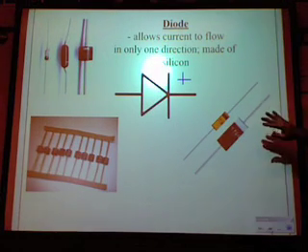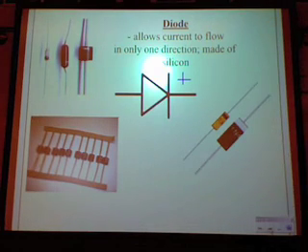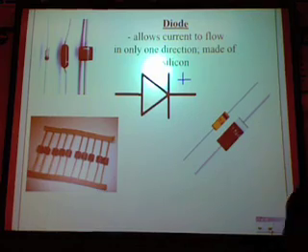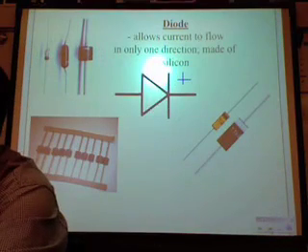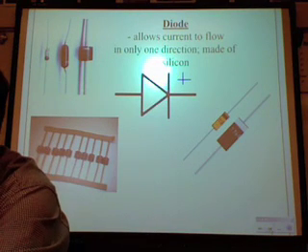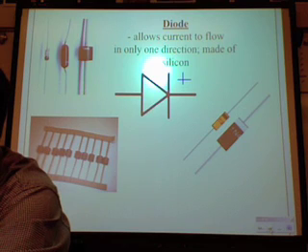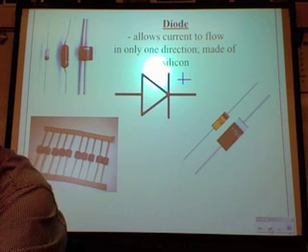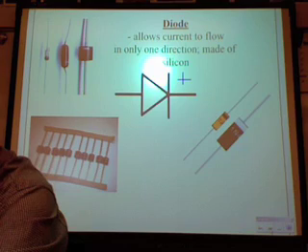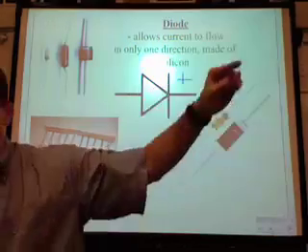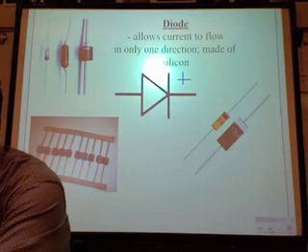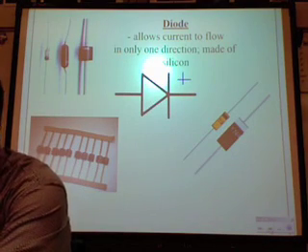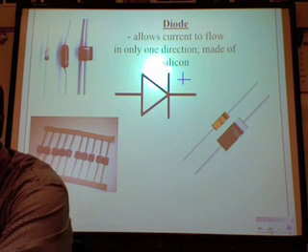And when you do that, then you're able to not just cut off the bottom, you're able to flip it over. Turn the negative into positives. So you can see this little guy here, it's pretty handy. This has 4 diodes inside it. You hook up AC here, and you get a plus and a minus there. It's not exactly like DC. It goes up, up, up, up in a whole bunch of mounds, okay? But it does turn AC into a kind of DC that will work for our purposes.